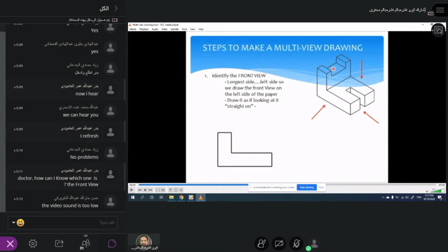But when you provide this front view without showing these hidden surfaces, then this drawing will not be sufficient, will not be professional, it will not be correct. So in order to show the surfaces and the edges which are hidden from the view, I show them by using a dotted line, and that we call the hidden views or hidden features. Okay.